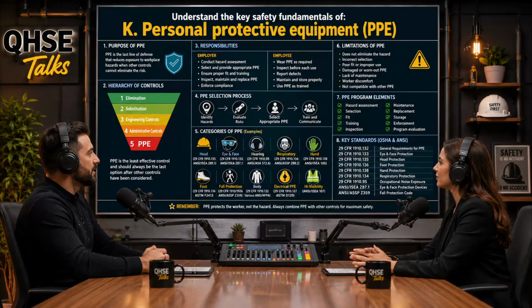So let's apply this to the real world. Our industrial hygienist takes air samples during the abatement. The lab results come back and show the ambient concentration of asbestos in the room is 3.0 fibers/cc. Well, since 3.0 is below our calculated maximum ceiling of 5.0, the full-face respirator is legally and mathematically adequate. It will successfully filter the air and keep the air inside the mask below the 0.1 PEL limit.